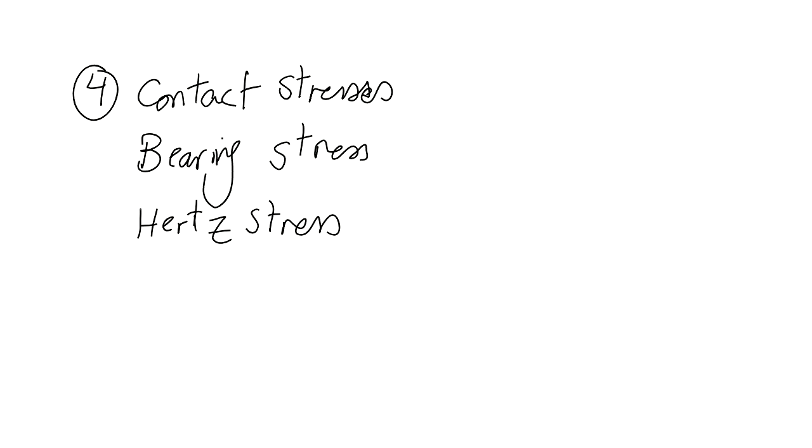So now we can say, as I said, the most common name is the contact stress. What is the contact stress? It is also sigma. Why don't we give it, guys, tau? Why do we give it sigma? Because tau is for shear stress, right? Yes, tau is for when your force is acting parallel to the cross section. But in this case, our force is still perpendicular to the cross section, so we cannot give it tau at all. Maybe because it has compression behavior. No, it's because of the direction of the force with respect to the surface.